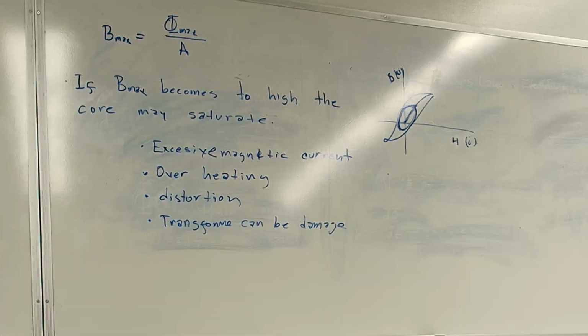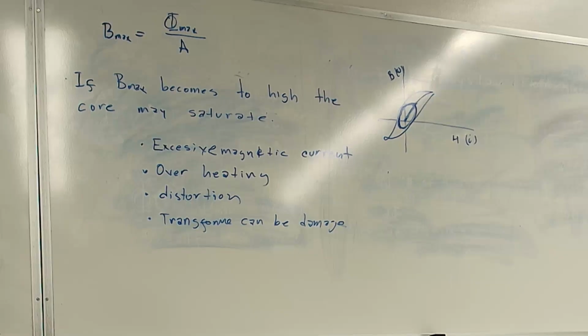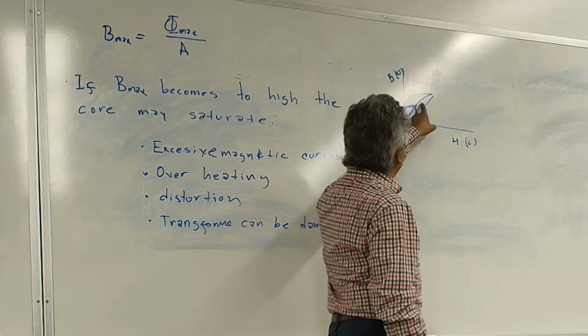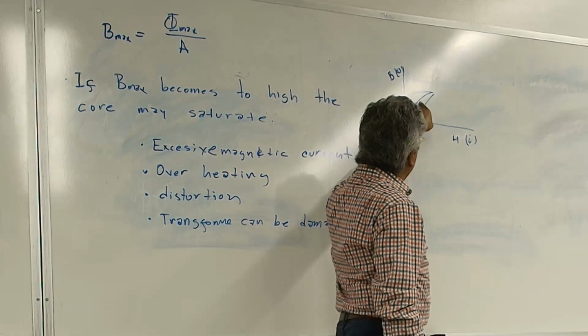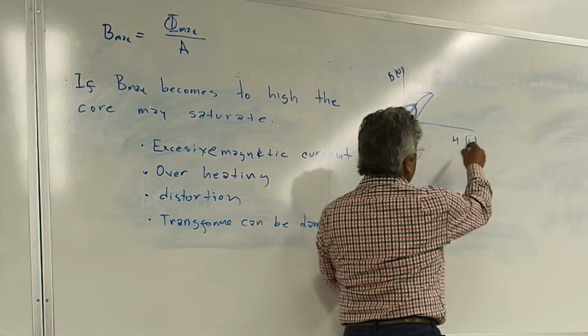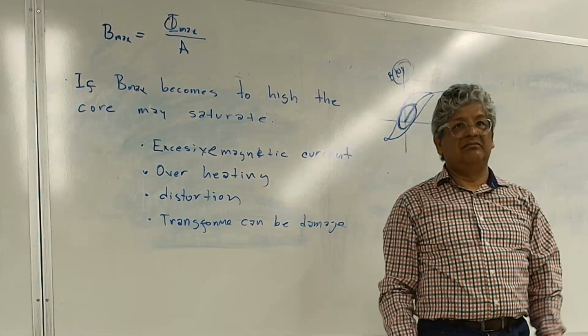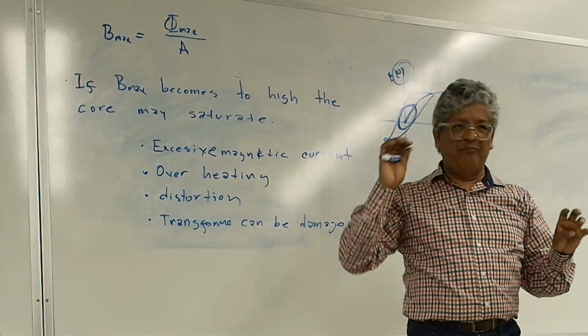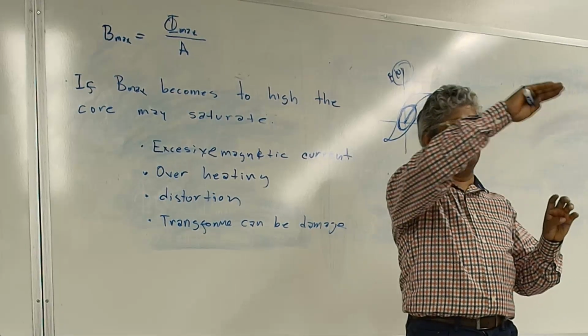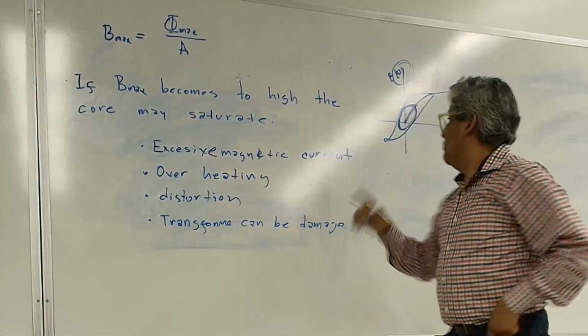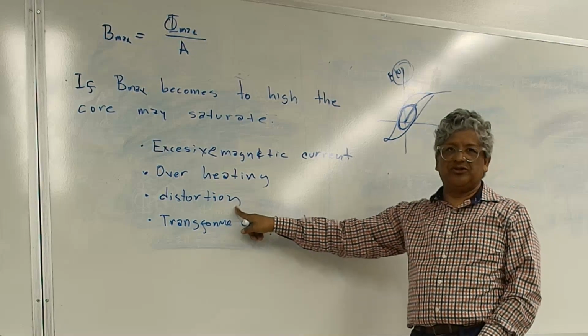What I'm saying is, if you have a transformer, you push current right here. And if you start getting into this nonlinear region, you can continue to push the current, but the voltage will not increase. I can push and push and push more current, but the voltage will not change anymore. So that is what we talk about with distortion.